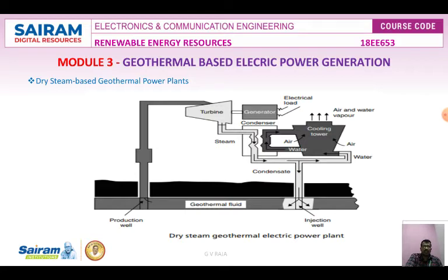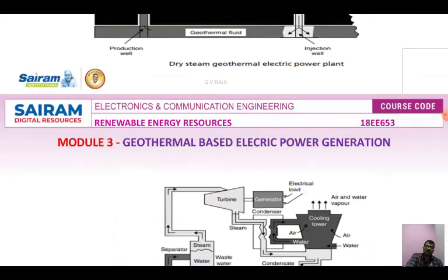It is very simple, requiring only steam and condensate injection piping and minimal steam cleaning devices. The dry steam system requires a rock catcher to remove the large solids, centrifugal separators to remove the condensate and small solid particulates, and condensate drains along the pipeline. So it is like a geyser type.